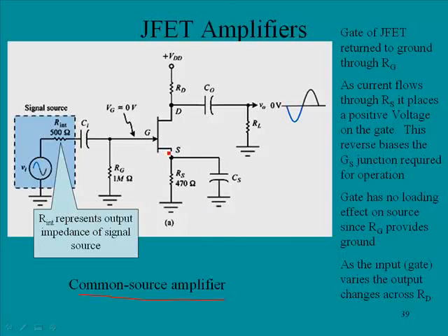It is an electrostatic difference that establishes the biasing for the drain, and it establishes a depletion layer. So the current flow is going to be through this leg right here. And recall, notice the large 1 megohm resistance right here, and the small output impedance of the signal source. So most of that signal will be felt right here and delivered directly to the gate.